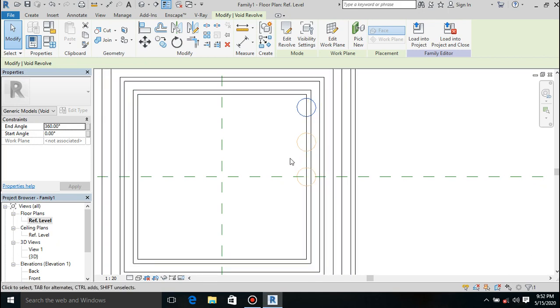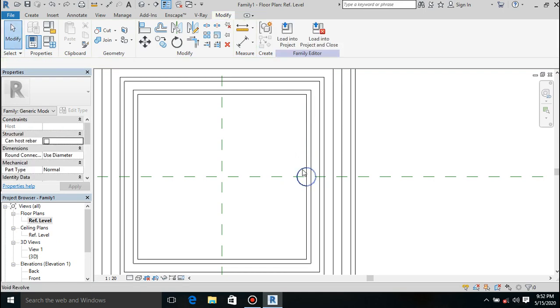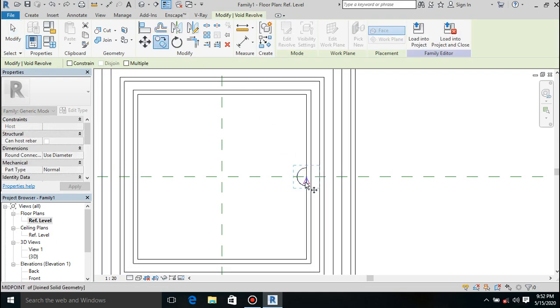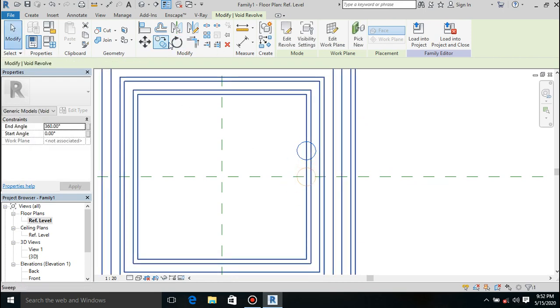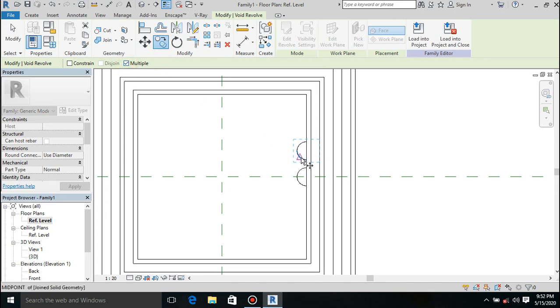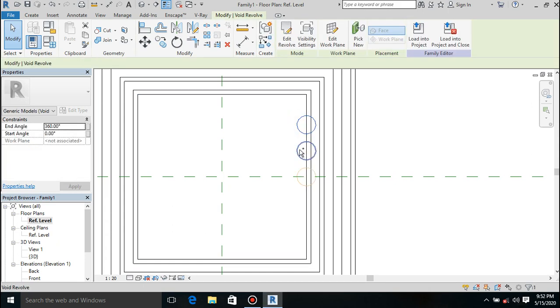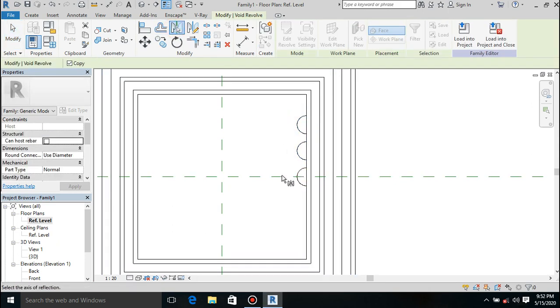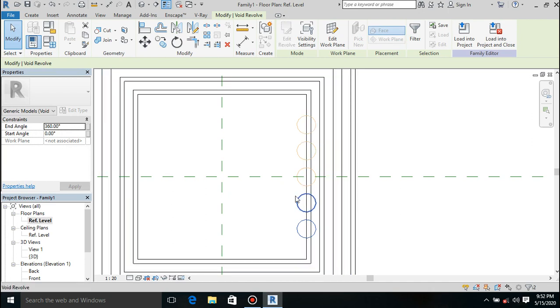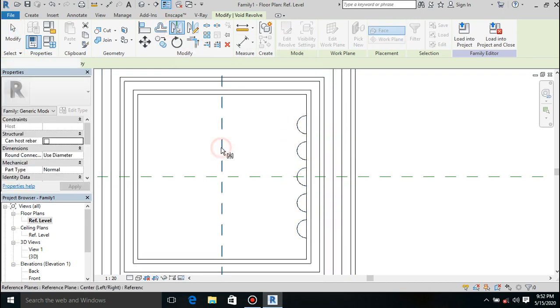Pretty sure 40 is going to work. It's a bit too much. Let me make it 30. Copy it this way, 30. Oopsie, I did not click on multiple. Copy it this way, 30. It's much better. At least I should have a bit of precision. Mirror. Click on this, select the rest, mirror again, click on this.